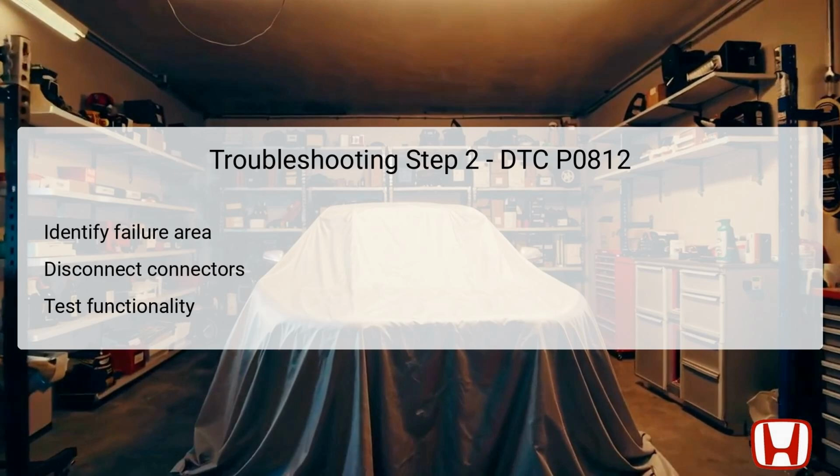You will need to connect terminals A and B with a jumper wire for the next part of this test. Terminal A is located at number 8 on the transmission range switch's 10P connector with a white wire, while Terminal B connects to body ground. After establishing this connection, turn the engine on and reevaluate the ATR switch condition through the HDS once again.